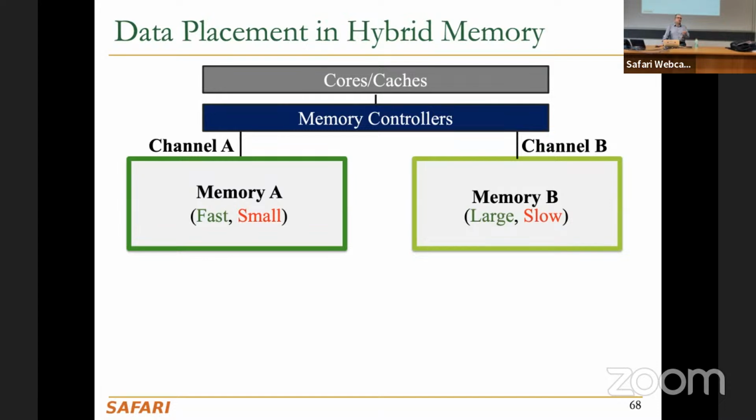For DRAM, to do a cold boot attack, you need to cool your DRAM a lot, to very low temperatures, such that the retention time is long enough that you can remove your DRAM from the system and put it on another system. But with non-volatile memory, everything is there, non-volatile, right? So potentially you can steal data and have security issues, and people have done research on that as well. Very good comment, I would say.